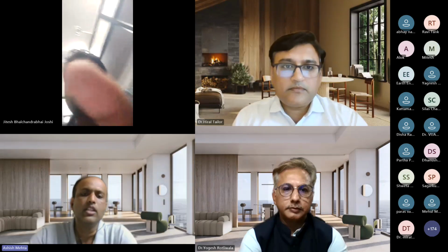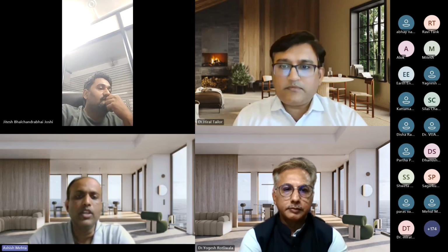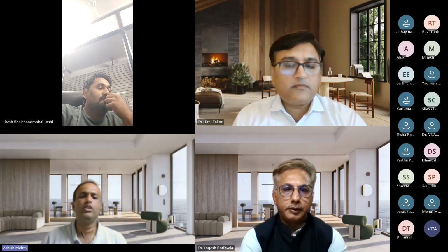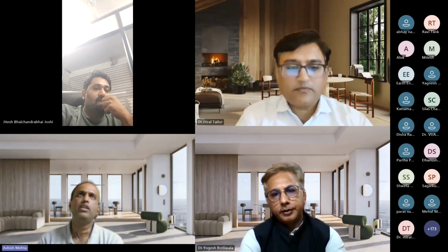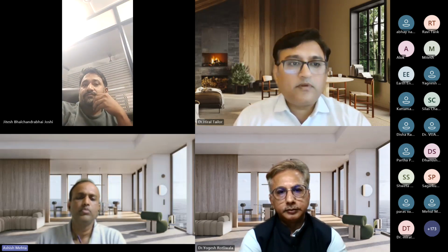Yeah. See, with new innovation, there are new approaches coming up. Like the new approach nowadays, which we are seeing at basically smaller levels, is related to the MVR system. Here, if your TDS and pollutant load, particularly COD, BOD, are at very low rates, you can go for adoption of a direct mechanical vapor recompression system. Here, the operational cost is as low as 35 to 60 paisa per liter. So it is very less. If we compare to the overall system, it eliminates your primary physicochemical treatment also. But the part here is that yes, it is capital intensive in the initial stage.